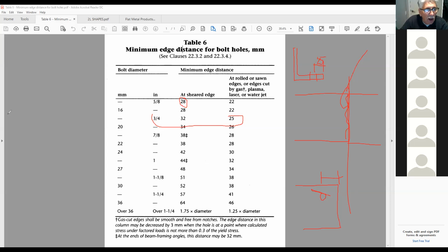So I have an angle here like this, and they have a machine that will punch right through the thing, and it gets broken off by shear. They wouldn't do this for an angle, but for plates. So if that's the way they're going to be fabricating the pieces, then you have to worry about these higher edge distances.